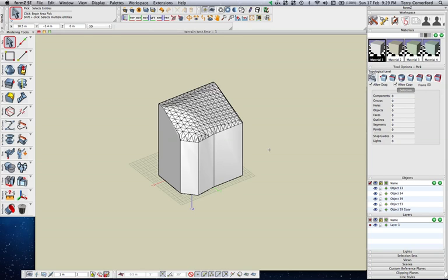In this particular case, for this example, in both the fill side of the embankments and also the cut into the side of the embankments, I'm going to go for a slope of 1:1, 45 degrees. But you could set that at any individual slope for both instances of cut and fill and make them different. So just for this case, I'm going to go 1:1. Now, first of all, I want to define where the building platform is going to be.